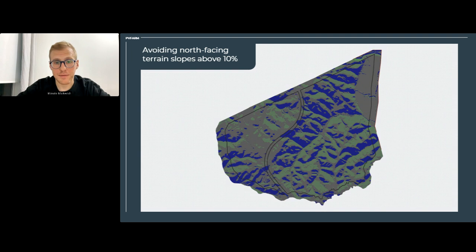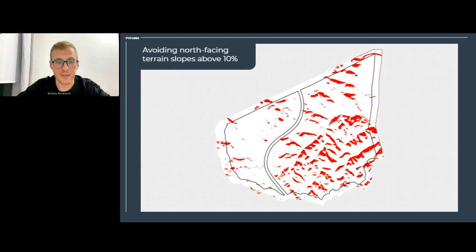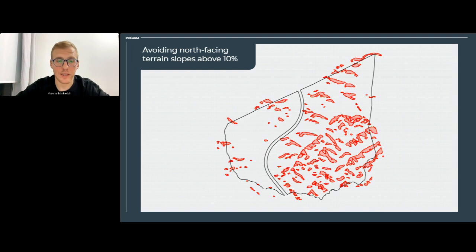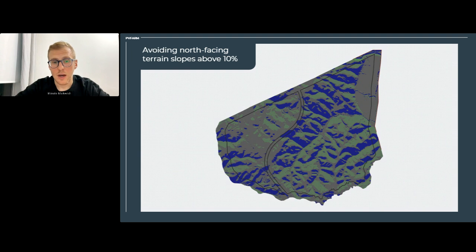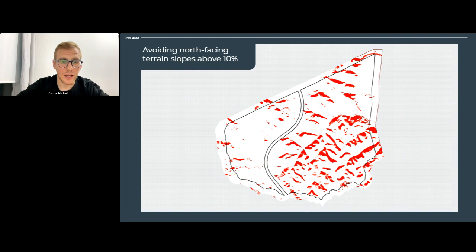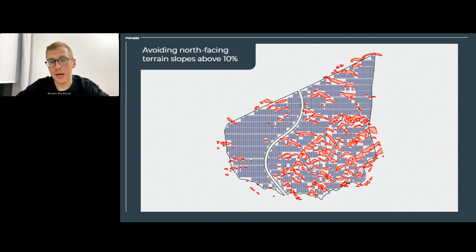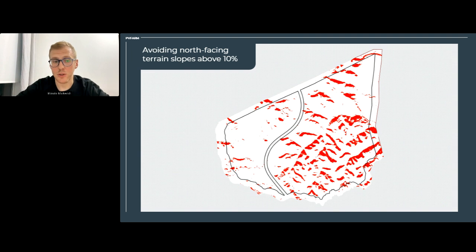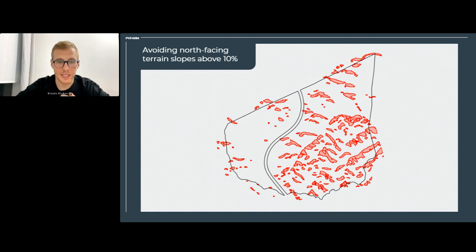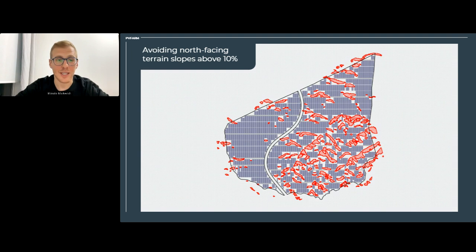And there is no one-way solution, and no one particular solution that works better. I think both have advantages and disadvantages, because when you go from terrain, you might end up with quite a diversity in your layout, and you will have a lot of standalone trackers, or small groups of trackers. While when you start from placing equipment and then doing analysis, you can end up again having some problems and more cut and fill, but you will have a more buildable layout, visually and maybe electrically. That's again feedback loops. It's important to consider a bunch of aspects, find the right balance, and understand trade-offs.